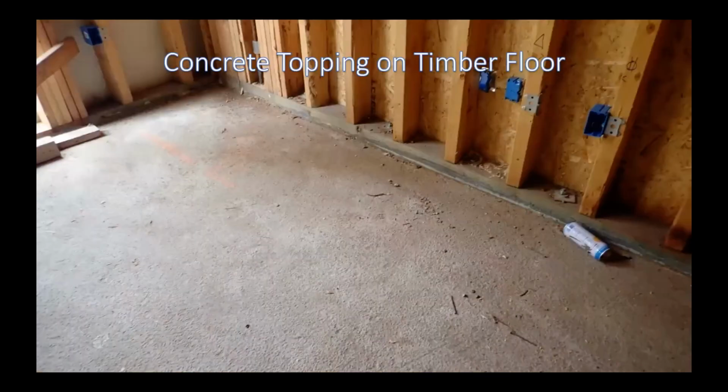We did see a few occasions where they even use concrete topping, whether it's for thermal mass or for sound improvements. It is a good way of achieving what you want with different materials. They often pour up against a double top plate, double bottom plate that they might form with enough depth to act as permanent formwork for the slab.